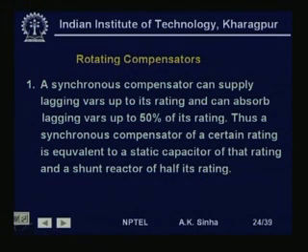Generally these are rated to absorb up to 50% of their rated capacity in terms of megavars. So, a synchronous compensator of a certain rating is equivalent to a static capacitor of that rating, because it can supply lagging vars with that capacity, which a capacitor also can do. Therefore, we can say it is equivalent to a static capacitor of that rating, and since it can absorb up to half of that rating, it is equivalent to an inductor of half its rating.